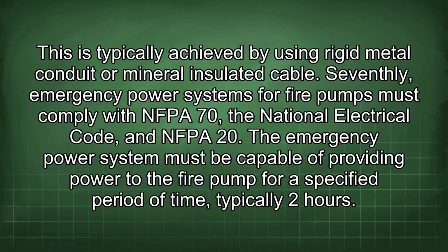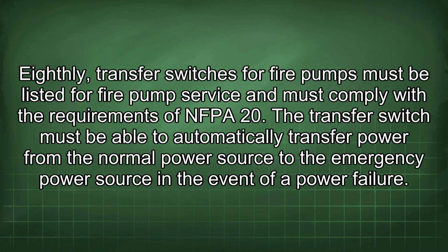typically 2 hours. Eighthly, transfer switches for fire pumps must be listed for fire pump service and must comply with the requirements of NFPA 20. The transfer switch must be able to automatically transfer power from the normal power source to the emergency power source in the event of a power failure.